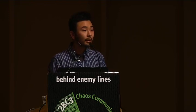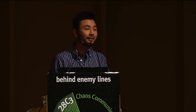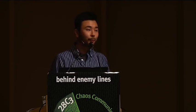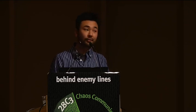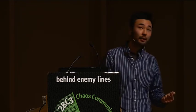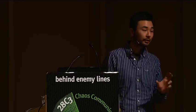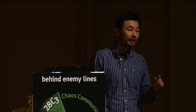Okay. One other question. What is the data rate of the data coming in from the Kinect sensor? Because one way to use this for mobile devices might be to downlink that and do the computation on the ground station. So for the depth frames, each depth pixel consists of 16 bits, and we actually use 11 bits of each depth pixel.